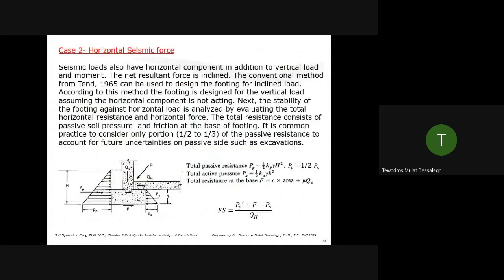It can cause sliding. That lateral force can cause lateral earth pressure. If you don't have enough support, you can have sliding. The only things resisting that lateral seismic force are friction and soil passive pressure on the other side. Otherwise, like a PA, it's moving and applying force, so the slab can slide, the foundation can slide. So it needs to be properly embedded, and there are factors of safety to be computed. This is where you consider the effect of the horizontal seismic force. You can go through this write-up and understand more.